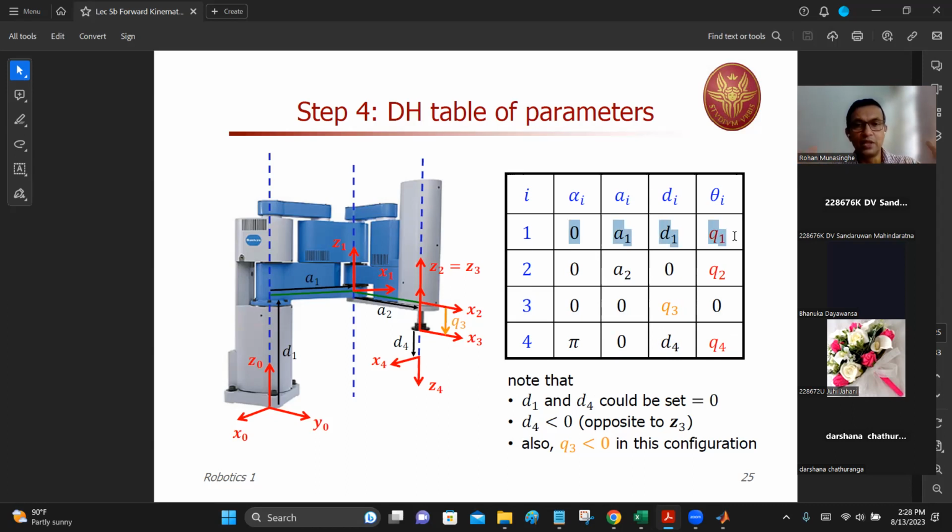In MATLAB, you get the homogeneous coordinate transformation matrix between, say, 0 and 1, 1 and 2, 2 and 3, 3 and 4. And after that, you get 4 homogeneous transformation matrices. You multiply them together. You relate the fourth frame, x4, y4, z4, with respect to x0, y0, z0. Okay? Then you know this point's coordinates, x, y, z coordinate of that point, and also this orientation with respect to the frame 0.